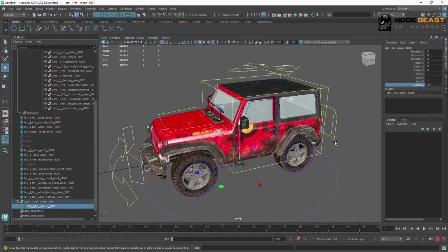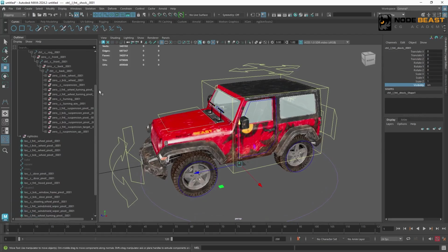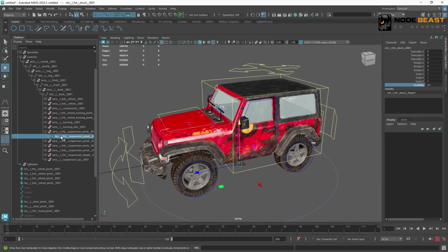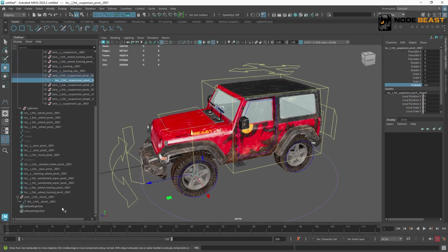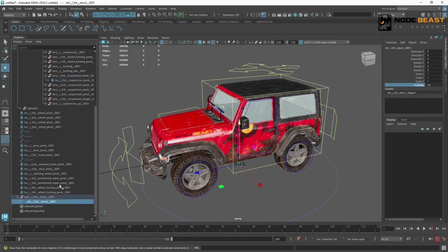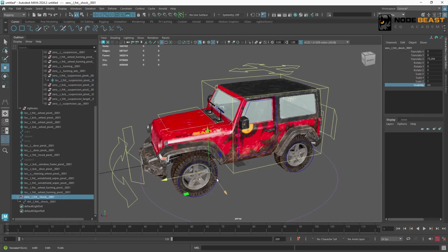Because we are going to connect the controller's translate Y to the corresponding locator's translate Y attribute, we are not constraining it. The reason is we only want to use this layer to control the locator. Above this locator, we'll have other layers of operations later, connecting to some other functions. So since we only need to do an attribute connection, its own position isn't that important.